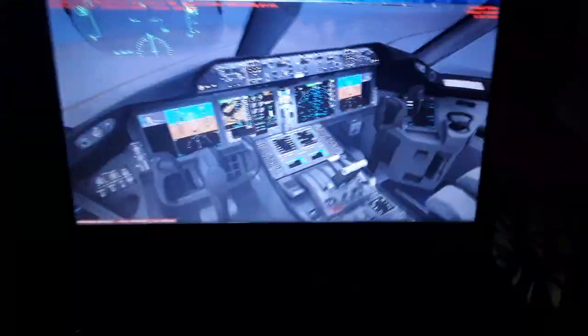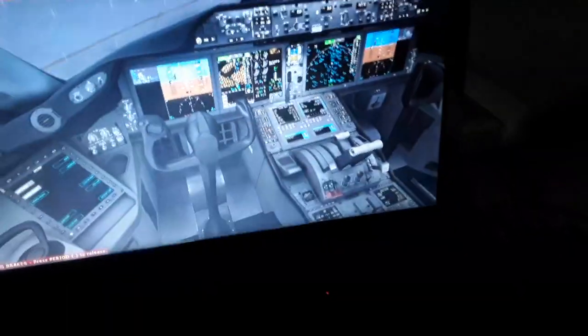Over here, I'm gonna show you now the horizontal trim stabilizer. When you fly, you can trim the horizontal tail of the aircraft to relieve the air pressures from the flight controls, from the yoke. Also to balance the aircraft in flight. So you have both manual and automatic. You have the auto trim function also.